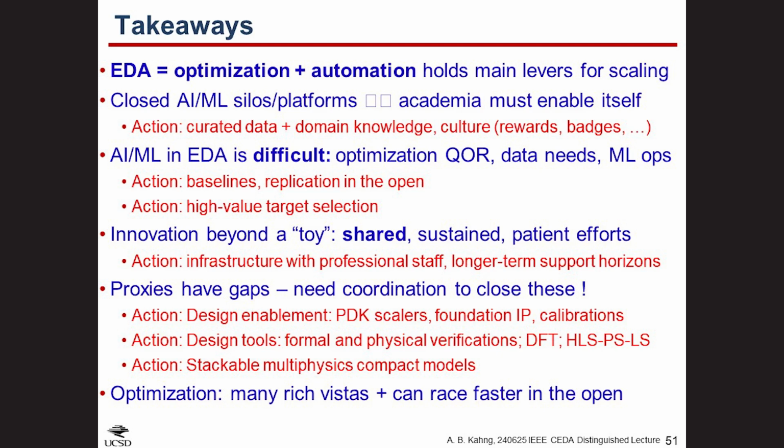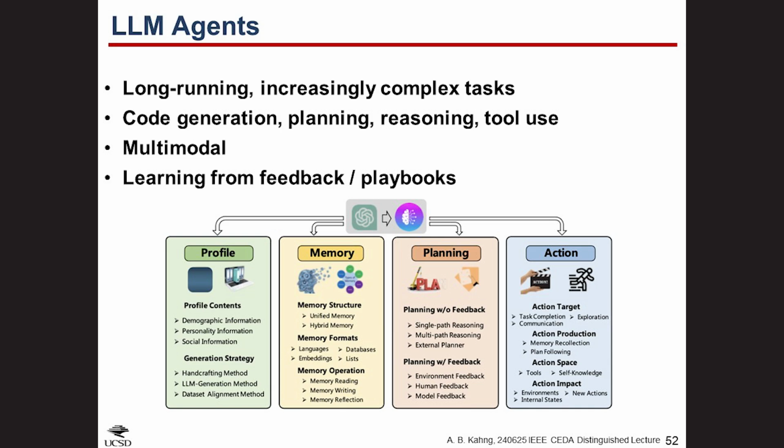And this is an AI accelerator in GF12 LP with 760 macros. And for this test case, hierarchical RTLMP actually gives a pretty good result when you evaluate apples to apples by completing place and route with the Cadence Innovus 21.1 tool. So this macro placer is free, the quality is excellent, and these are final outcomes of a hybrid open plus closed source flow.